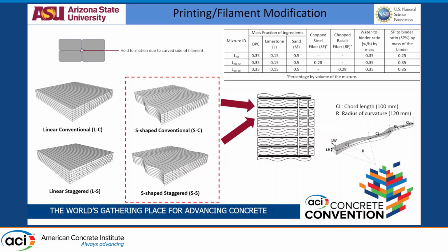So we usually use a circular nozzle. A square nozzle has its property advantage. Circular has its advantage. For example, if your filament is not technically linear, when you use a square, there will be a twist in the filament, while circular would not have that effect. Circular will print a similar cross-section filament even at a twist. Like if you have to go 90-degree angle, you don't have to stop and start. You can just keep on printing. So those kinds of advantages are there. So we usually tend to go with a 20 mm circular nozzle diameter.